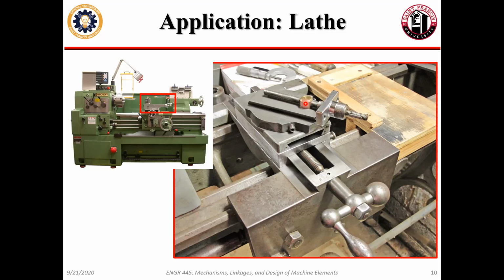What you see is a fairing covering up the screw, because of how far down the flaps go, they need something to cover it when you come around to land. So you've got these things all over the place, because screws are really easy ways to make a rotating load from, say, a motor, a linear translation and a linear force, without really occupying a ton of space.